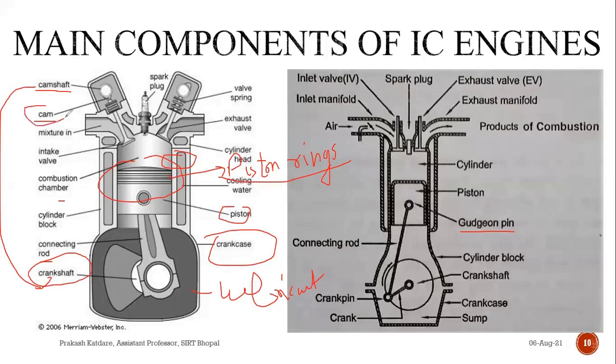Also, there are cams. What are cams? These are an integral part of the camshaft and are designed in such a way as to open the valve at the correct timing and to keep them open for the necessary duration. What do you mean by necessary duration?